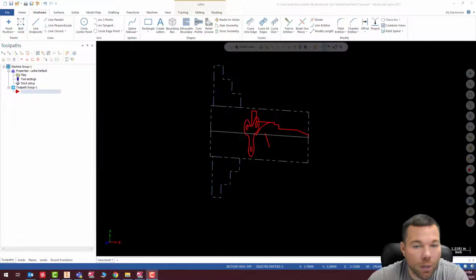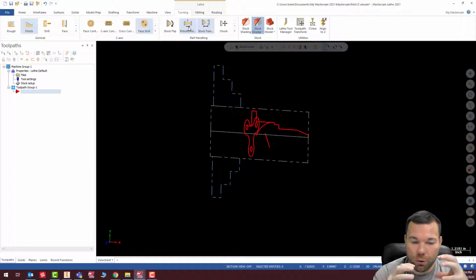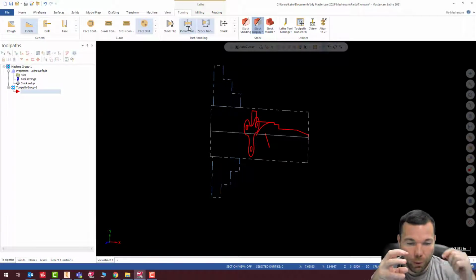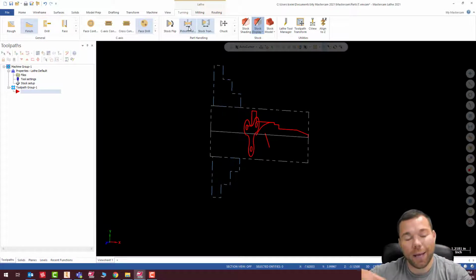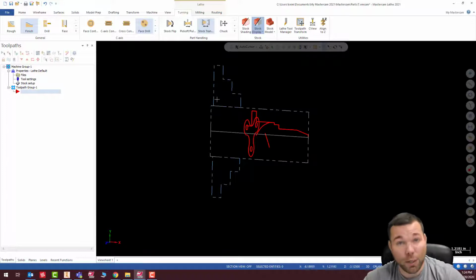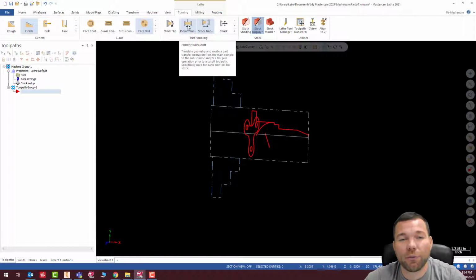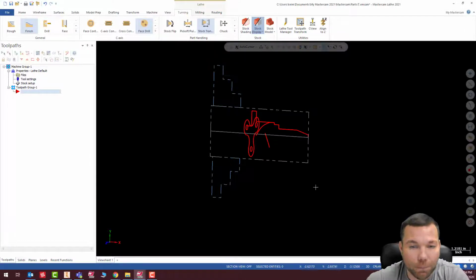That looks good. So what I mean by pick off is that we're actually going to do a pick off cutoff. I'm going to come in with my spindle, grab the part, and cut it off while both spindles have hold of the part, and then once it cuts off, I'll transfer that back and we'll do the back side. It's not what your book tells you to do. That's okay. If you just did a stock transfer, don't worry. I'm just showing you this so you know how to do it for the future. I know you know how to do a stock transfer now because I've already had that in a past video.